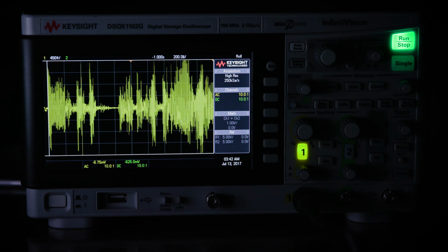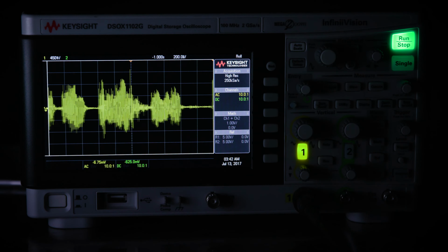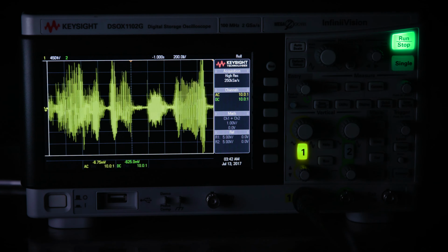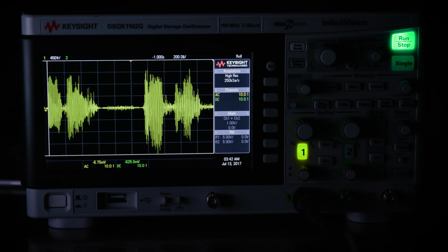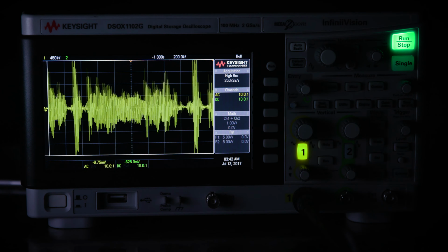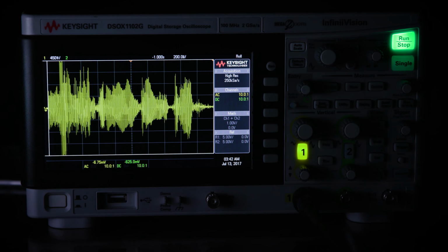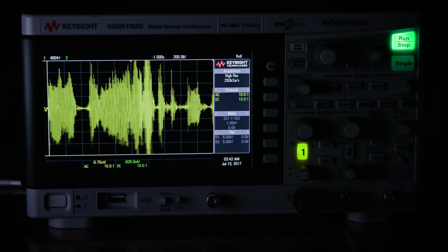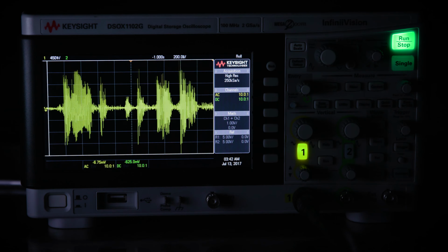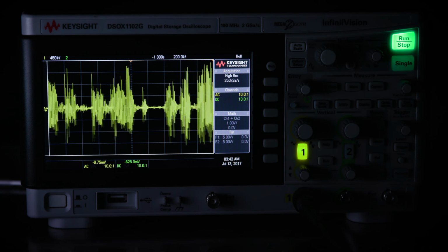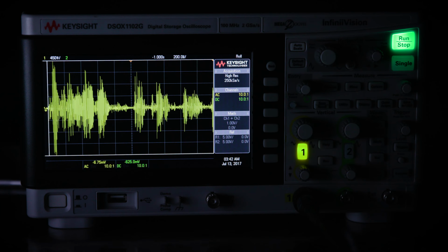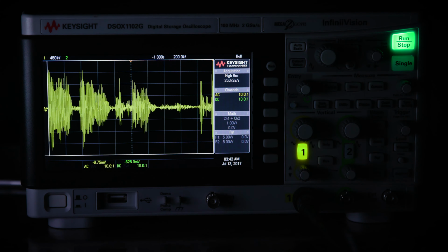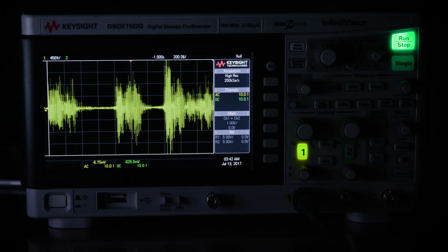But if it's contributing no noise to your system, you've got some really garbage amplifiers out in front, and you need to work on them. So we start in an instrument with a noise budget on how much noise is contributed by the various pieces of the chain. And then we go off and say, okay, you front end designer, you get so much noise. A to D converter designer, you get so much noise. Somebody else gets so much noise. And of course, that all gets renegotiated as time goes on. But you have to start from an overall system viewpoint of how you divvy up the noise between the pieces of the design.